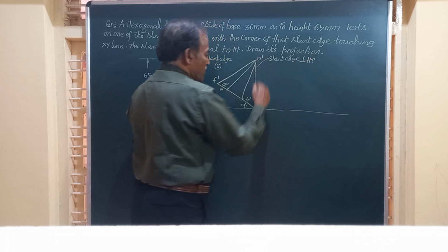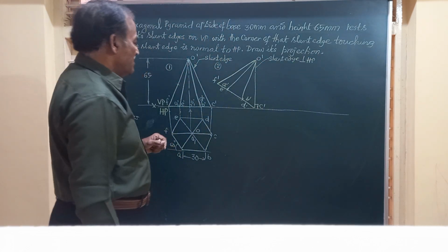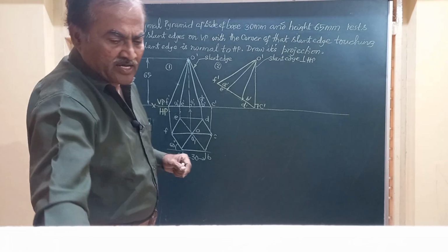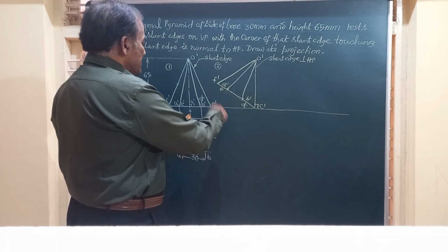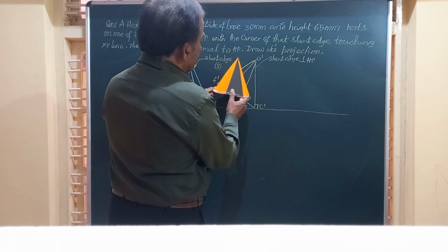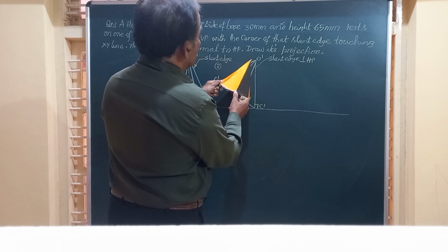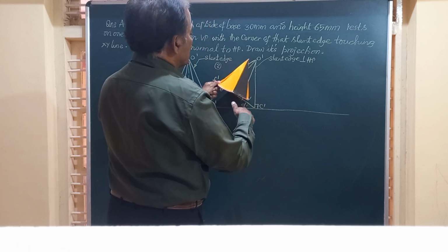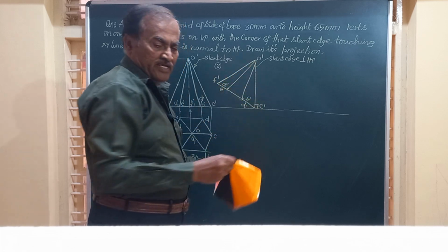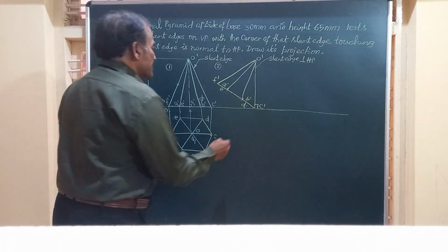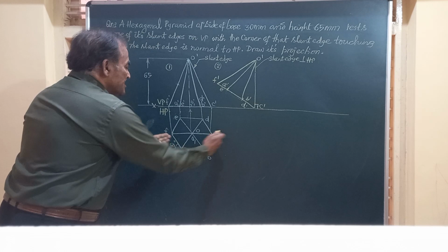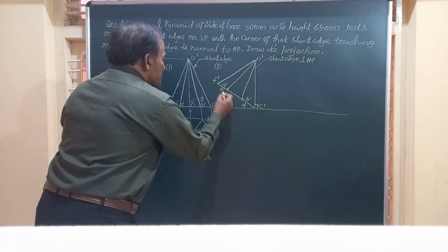You can see this is OC is perpendicular to HP. Friends, let us obtain the corresponding top view for this. Friends, have placed like this, and now what happens, you will be able to see the complete base of the solid and also the vertex along with some slant edges. So only the thing is, this figure FC gets shortened.